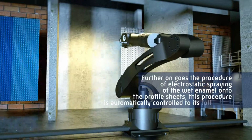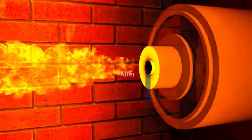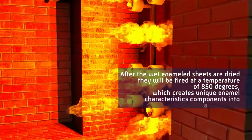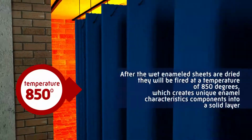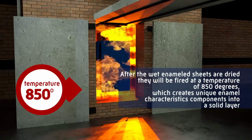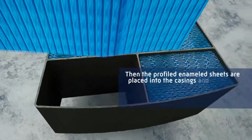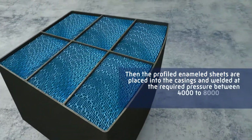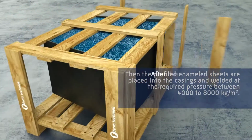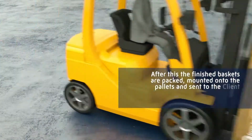This procedure is automatically controlled to its full extent. After the wet enameled sheets are dried, they will be fired at a temperature of 850 degrees, which creates unique enamel characteristics components into a solid layer. Then the profiled enameled sheets are placed into the casings and welded at the required pressure between 4,000 and 8,000 kilograms. After this, the finished baskets are packed, mounted onto the pallets and sent to the client.